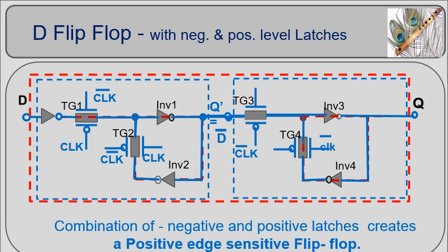The first latch, known as master, with low enable signal, operates in transparent mode, propagates the input data D into the latch. The second latch, known as slave, with high enable signal, operates in transparent mode and latches the propagated data to the output terminal Q. The combination of negative and positive level enable signals creates a positive edge transition clock signal. After the clock transition, data transferred into hold mode latches remains stable.